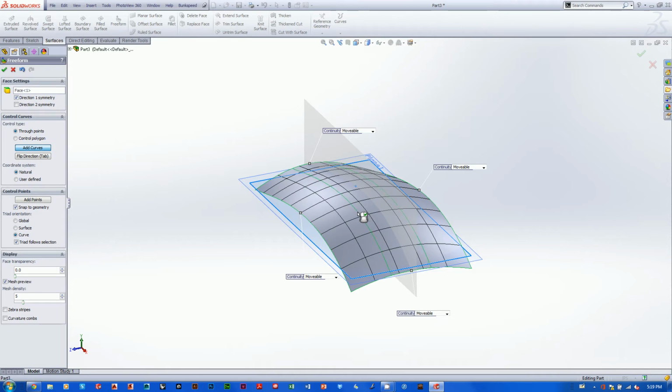It's a little bit hard to explain until you get in there and add some extra ones and play around with it, but wherever you'd like to create a freeform into your shape, add a couple extra isoparms and it adds a little bit more body to your piece. So I'm just going to add one now because I have symmetry turned on. You see it adds one to either side of the surface, excuse me, and I can add as many as I want at any time.